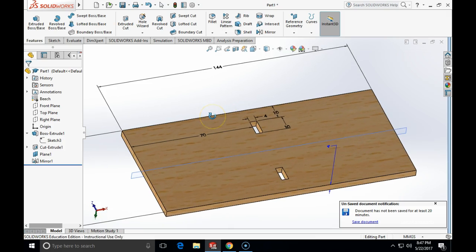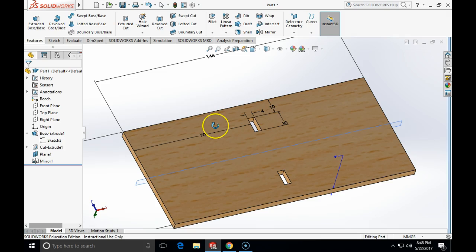In the next part we are going to get introduced to the new placed command, which is the hole command for making the circular cuts. And then we are going finally to make our first assembly, in the assembly mode, where we will assemble the 2 parts into an end product and then make the drawings. And this will give us the full overview of the entire SOLIDWORKS workflow.